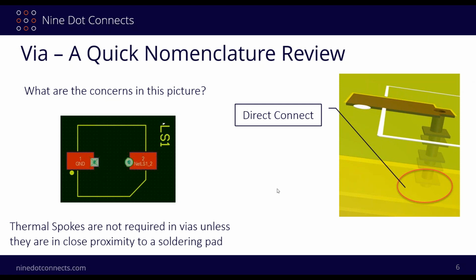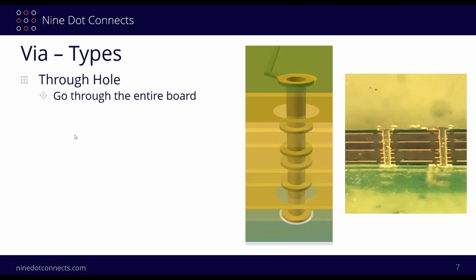All right, let's move on over here. I want to go through all of the via types over here. Some of them, you know, probably like the back of your hand. One thing I've always found interesting, though, and this is a nice feature of Altium Designer's 3D, is that we can actually look at this thing as it probably would look. It's an ideal situation, but this is generally how it would look in the design itself.